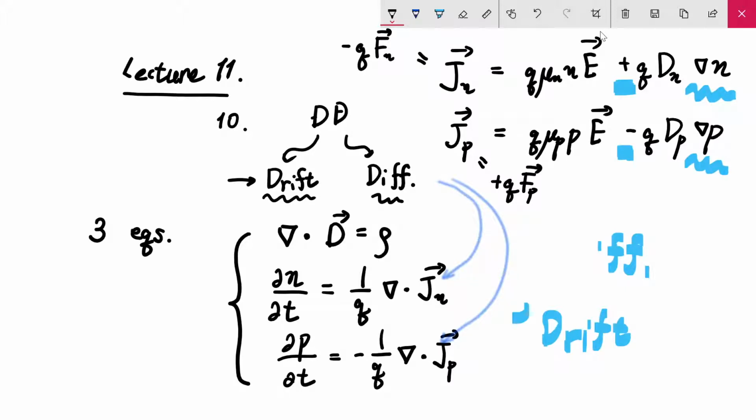So initially, when we consider just the fluxes, then yes, as we expect, the diffusion term has the same sign and the drift term has a different sign. However, since we have multiplied by different sign quantities, minus q and positive q, that's the reason why we have different signs in here. So please remember these sign differences.